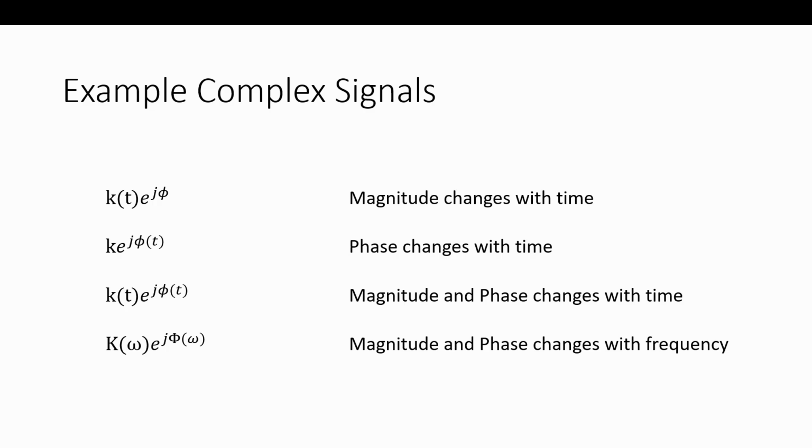So don't think of phase if you picture that image of when it's first introduced to you as here's a sine wave and here's another sine wave. That's a time delay. It's not a phase shift, it's a time delay. That horizontal axis is time, that's a time delay. And it really can mess you up if you associate it directly with phase. Phase is a rotation on a complex plane, and that's it. And then we can explain how we can map a time delay to phase and stuff like that.